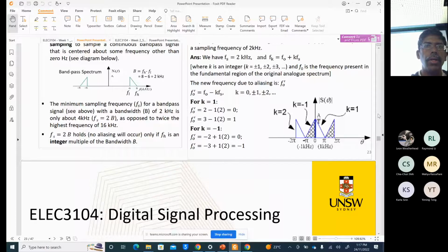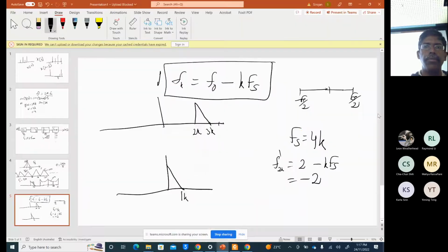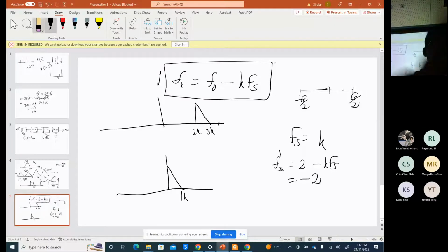Yeah, okay. So it's actually 2K is enough. So if we have the sampling frequency here, this is the bandwidth. Bandwidth is 1K now. So with 2K, twice the bandwidth, we can actually bring it to the baseband. Why? Because with 2K, 2 kilohertz becomes 0.